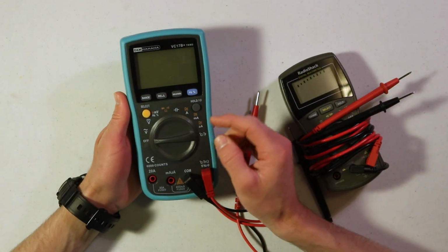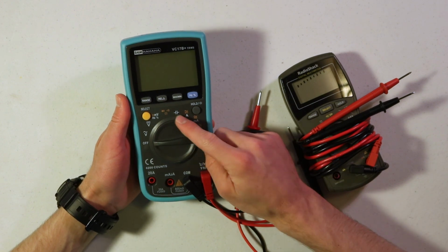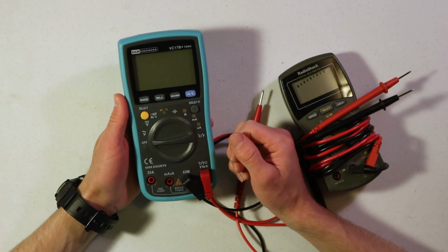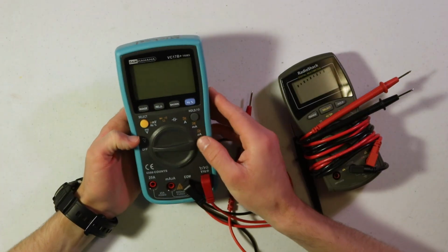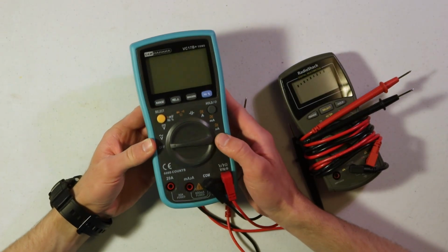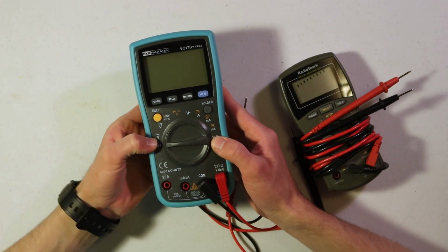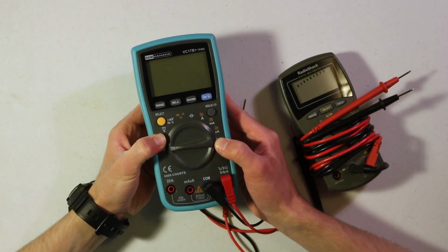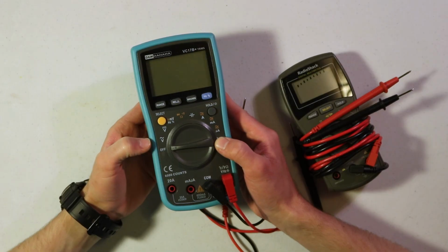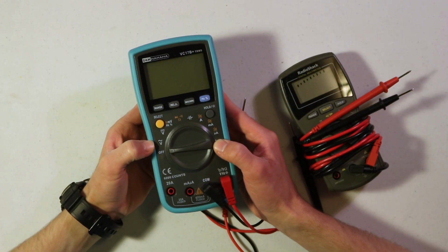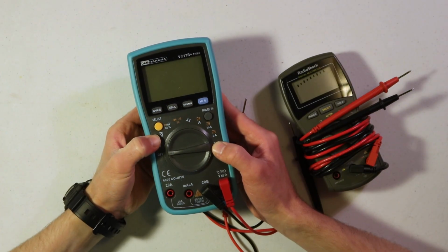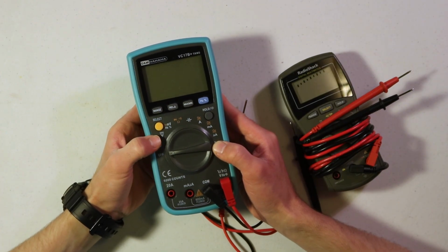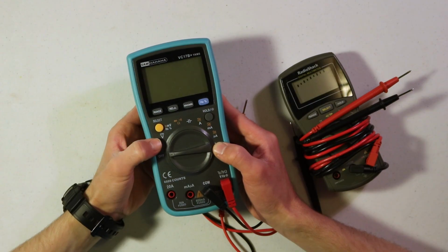The next thing to notice is the mode dial, which you can turn to the different function that you want to measure. So the first one here on mine is voltage, and you can see that we've got two different voltages here. We've got V here with a little wavy line on top, and then V with a solid and dashed line on top. And whenever you're talking about circuits like this, the wavy line is alternating current, and the dashed line with the solid line, or even just a solid line, is your direct current.